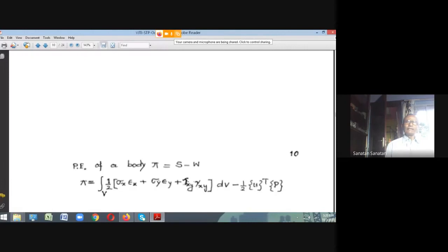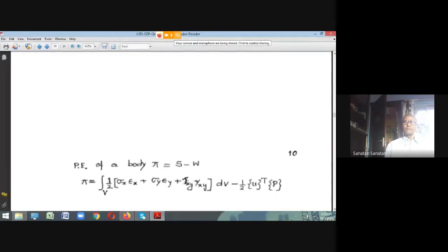But to summarize, you can find the solution to a stress analysis problem analytically. You determine the stress function, which involves arbitrary constants, and these constants have to be so selected that it satisfies the two equilibrium equations and at the same time the boundary loading conditions. That's the crux of the whole problem.